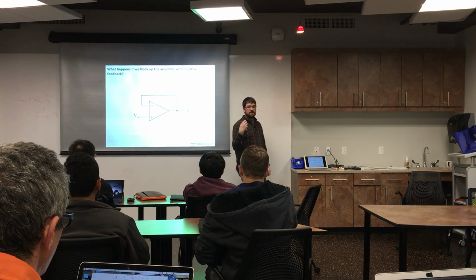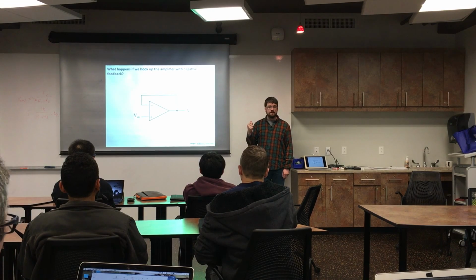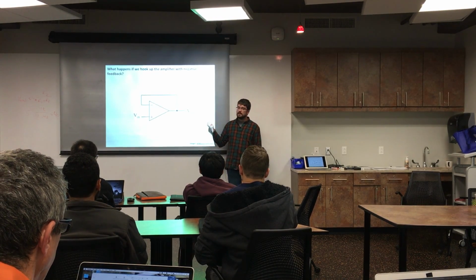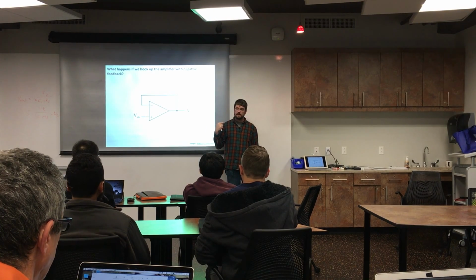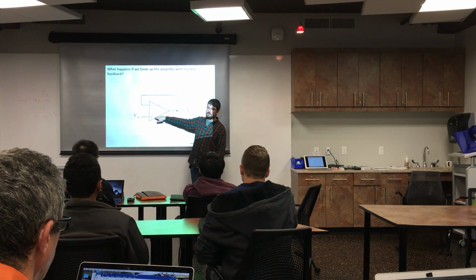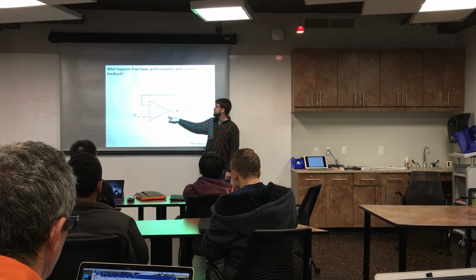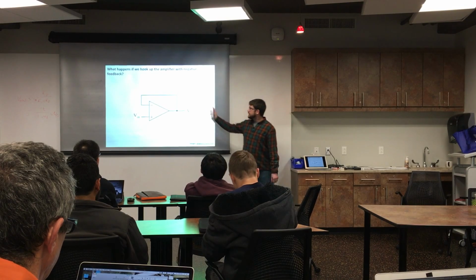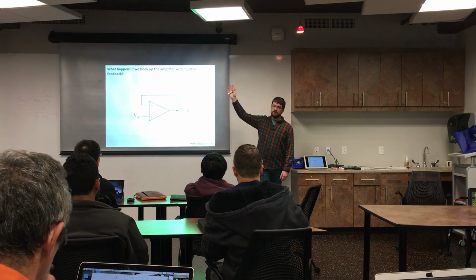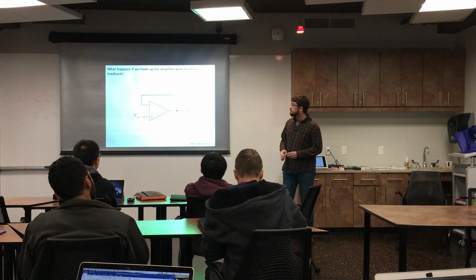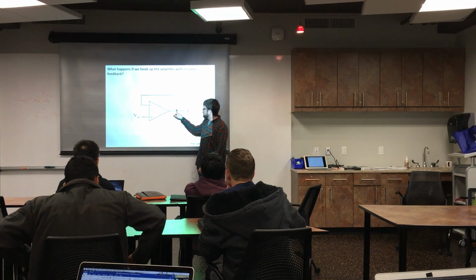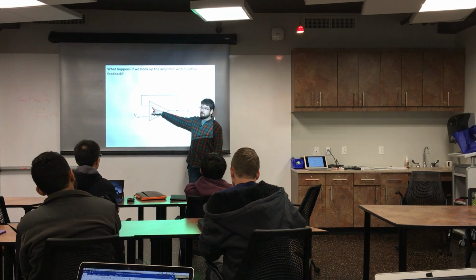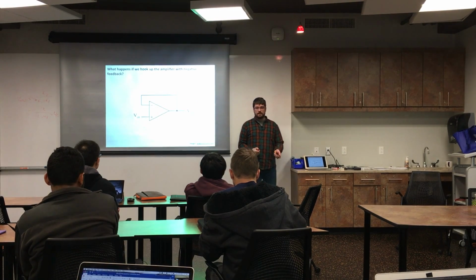So what's the op amp going to do on its output? So the non-inverting input is more positive. So this is 0 and this is +1. So it's going to output plus something. And if this were an open loop circuit, if we didn't have any feedback, this would go to the positive voltage rail, right? And it would go to saturation. But it's not. So this voltage starts increasing. We're looking at a very, very tiny time scale here. And starts feeding back into the inverting input of the op amp.